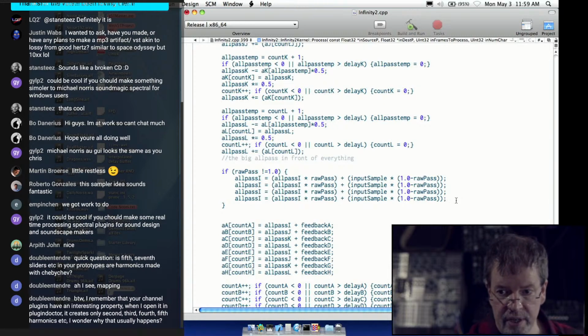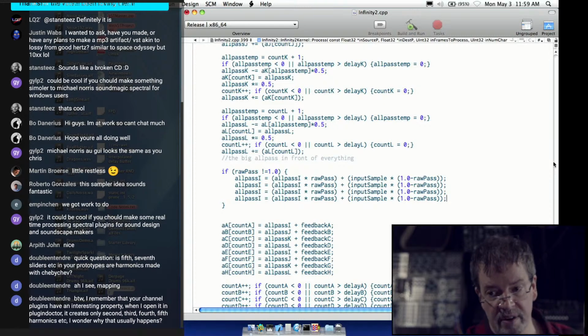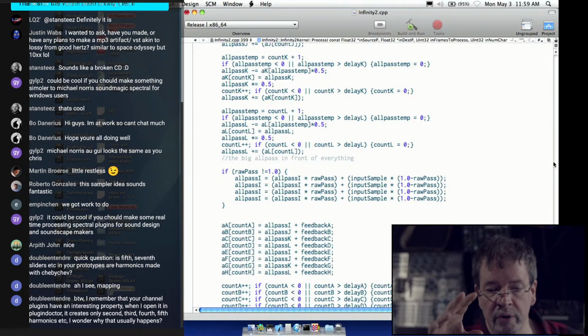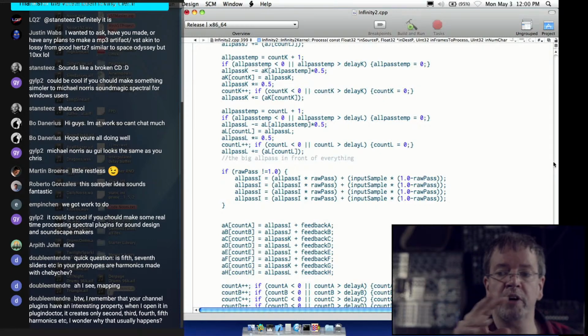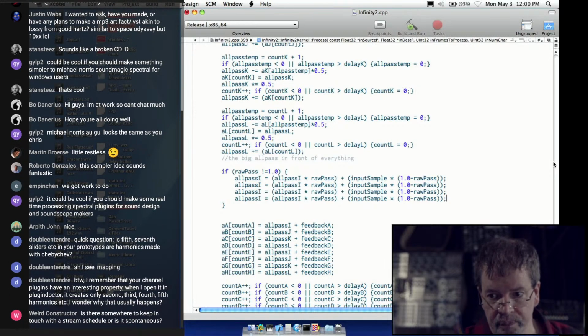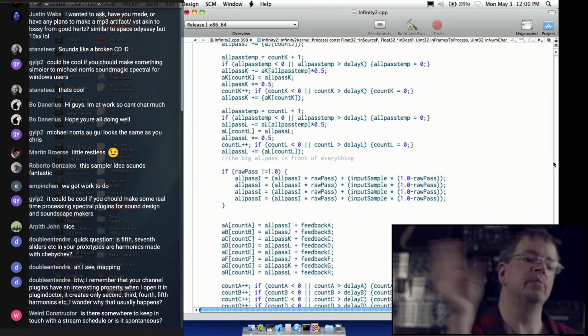The channel plugins, depending upon how you've got them set up, are either the density algorithm or the spiral algorithm. And those are variations on a sine function. So the reason you're only getting second, third, fourth, fifth, and so on harmonics as you push it harder and harder is because it's a soft clip rather than a hard clip. If it was a hard clip, you'd get some of all the harmonics forever, including the ones that alias. But if it's a soft clip, you have to go harder and harder into it to generate more harmonics, and you're making a kind of ladder of harmonics as you keep going. And that is why the plugin doctor only shows you that rather than showing an entire array of harmonics like with hard clips.